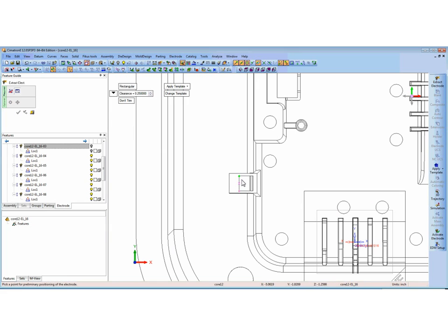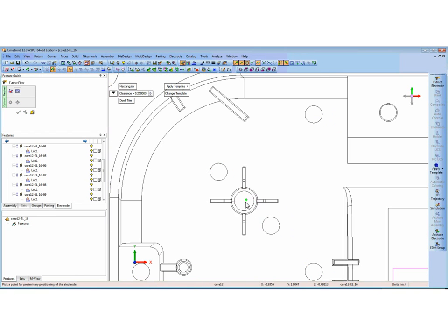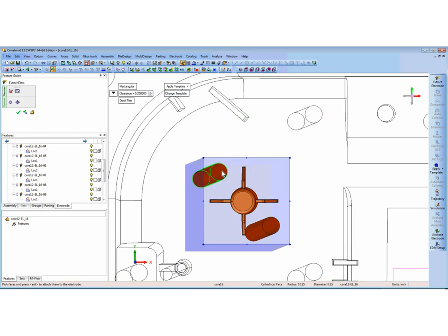And this one is kind of challenging to pick the surfaces that I want. One little trick that I'll do is I'll put the electrode way over here where it's not picking anything. And then I'll do a right to left box pick, which will pick up only what I care about. And then that same fit and center will put me right on location. And this will be the last one that we do, and this one. Don't want those.